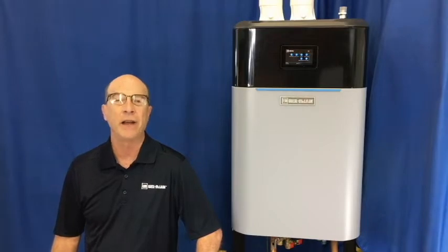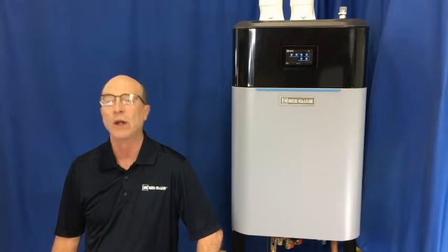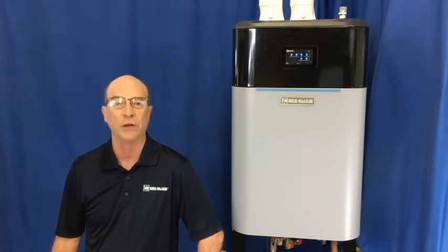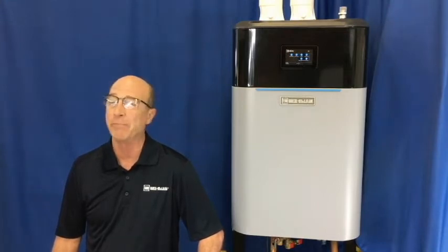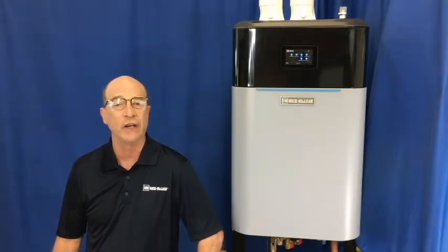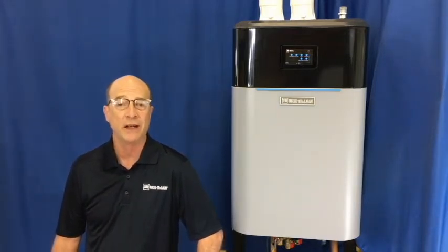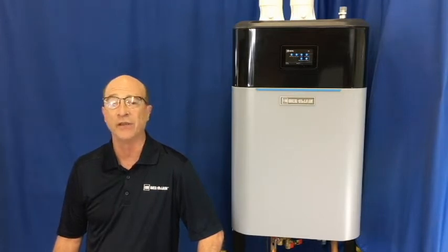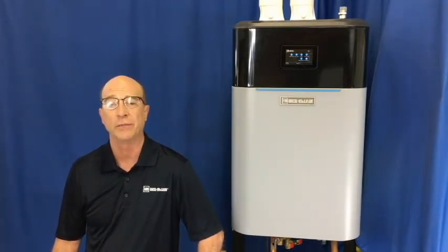I'm Brian, and today we will be discussing our ECO Tec boilers and how to navigate the control and run the wizard for setting up the boiler. The design of our new ECO Tec boiler allows fast, easy, and flexible configuration and adjustment. The control can be set up manually by going through each section of the contractor menu, then choosing the appropriate value for each parameter. Or you can use our wizard setup program to guide you through the setup with a series of easy to understand questions.